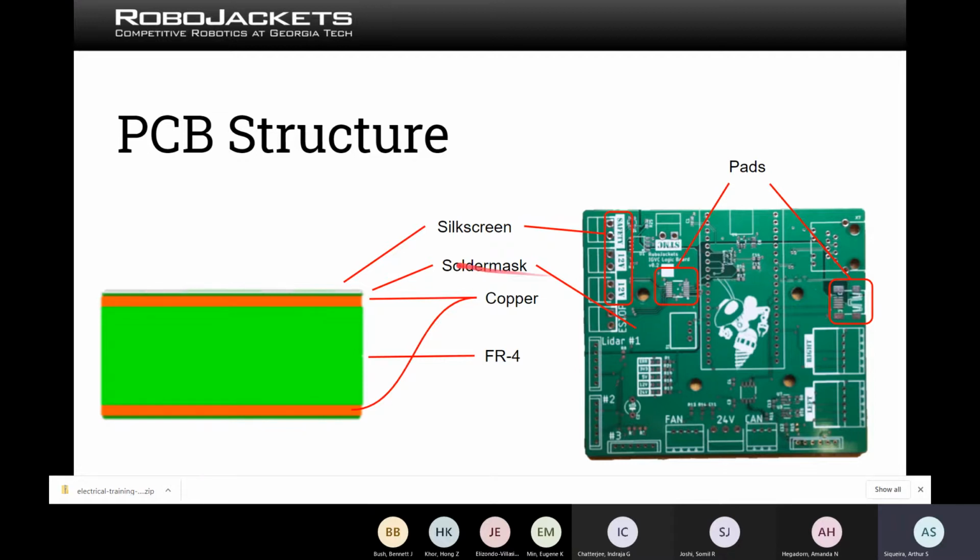And then apart from that, there are also some spots in the PCB that you see don't have solder mask on, because at some parts of this PCB you actually want to have a place in which you can solder stuff, and you want the copper to be exposed. If you want, for instance, to solder a resistor, or in this case right here to solder an IC, you can then have those pads available, having their space for putting a component.